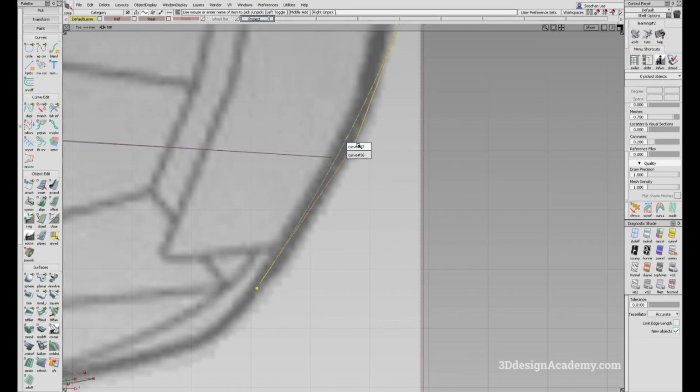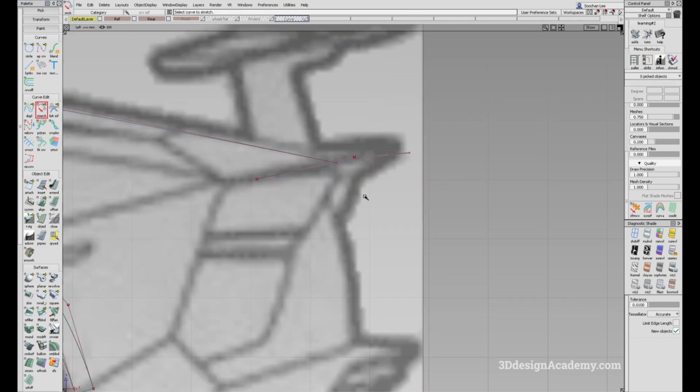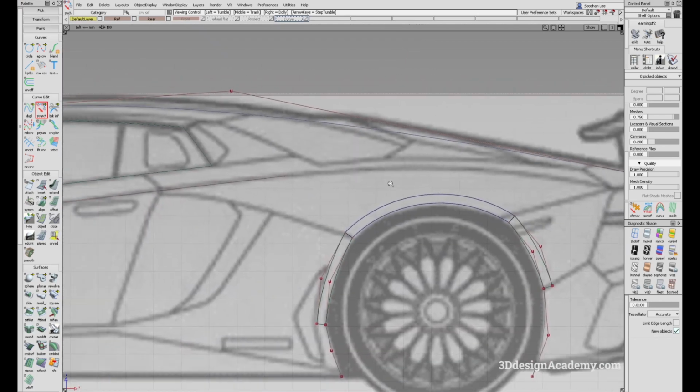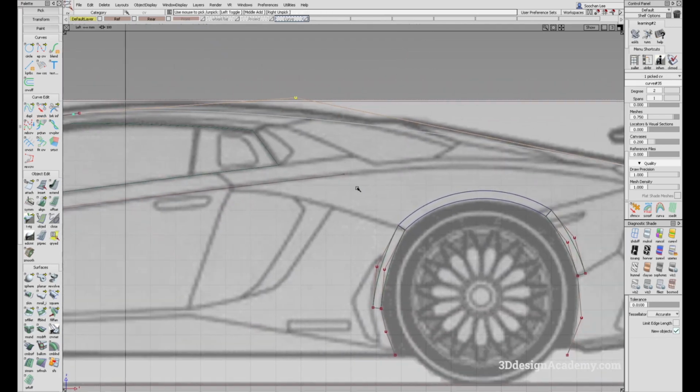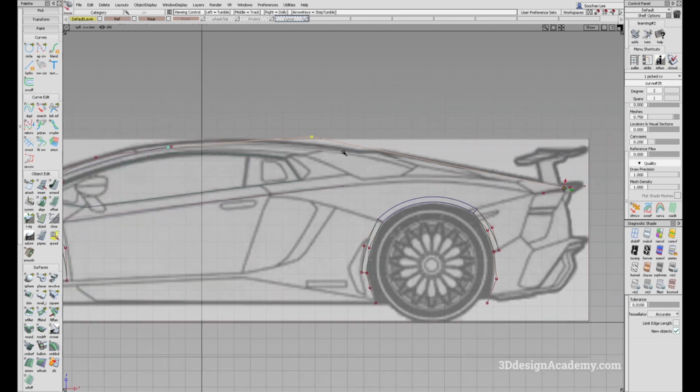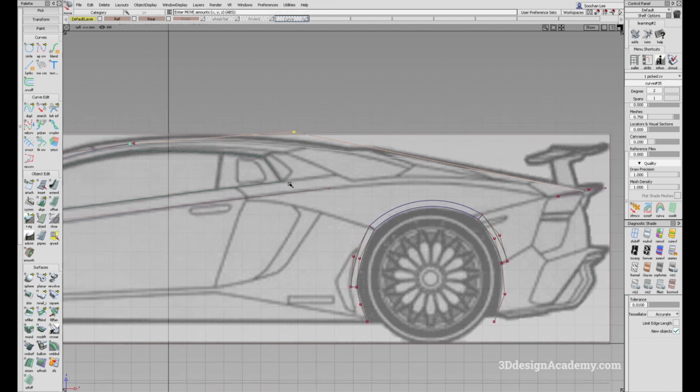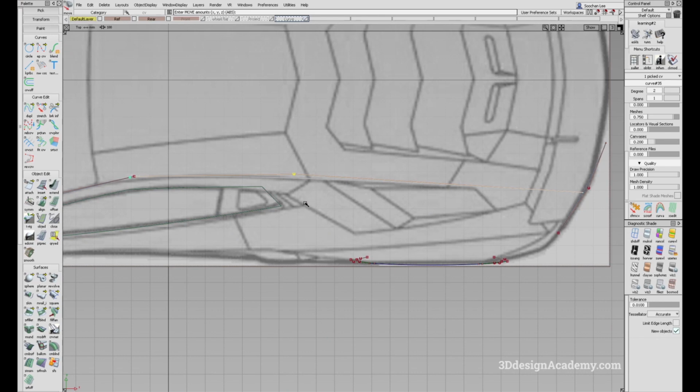So I'm going to grab this curve and put it on a different layer, so that's hidden. Let's say curve. I'm going to extend this curve a little bit and use the stretch tool to snap it over here like this, so that it's exactly located where I want it. Right now, because of the CV move that we just did, I think it's a little bit lower. So I'm just going to add a little bit more crown in order to compensate for that.